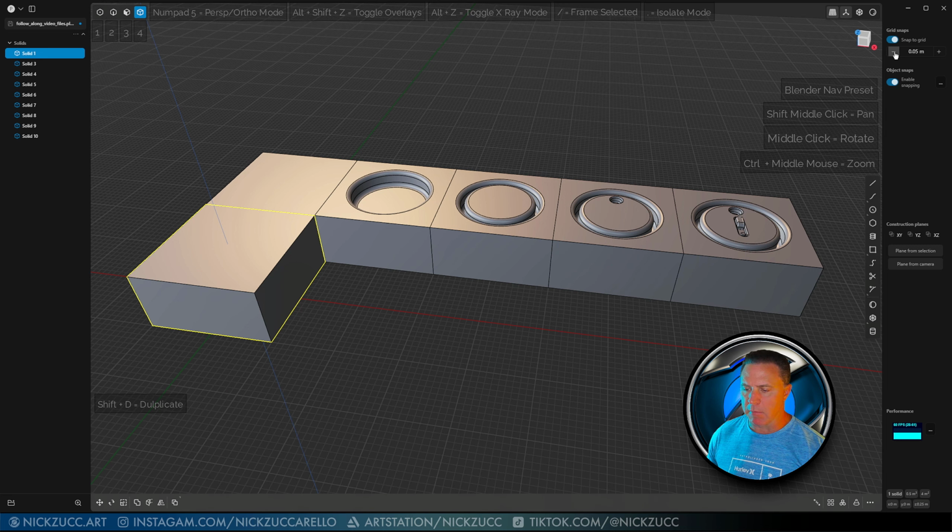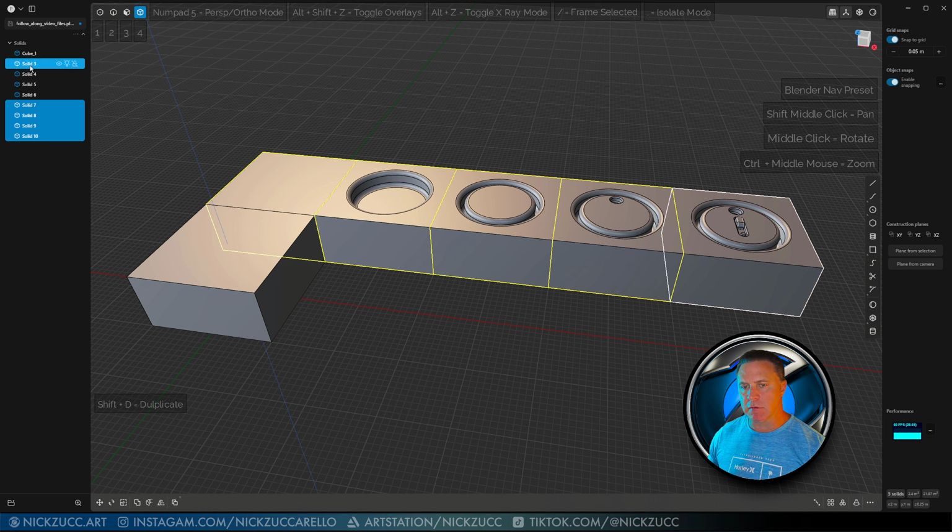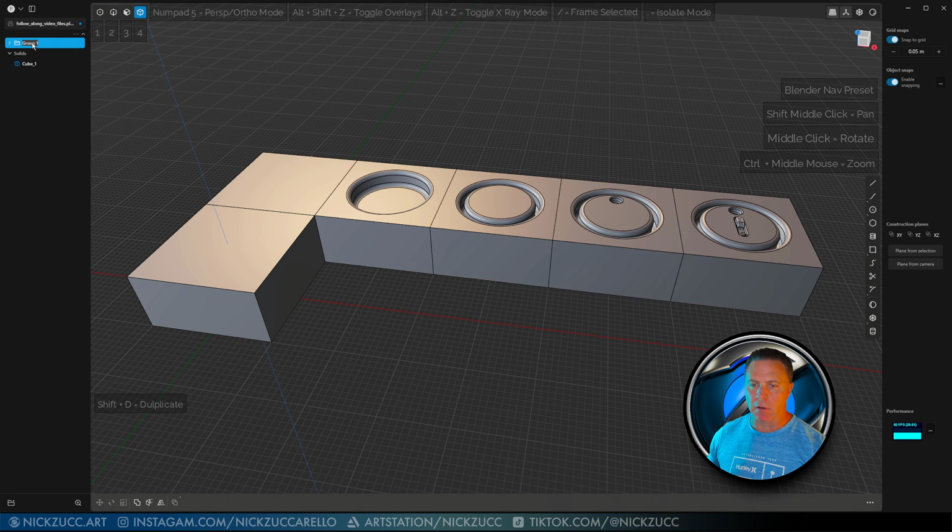And then if I want to put all of these in a group, just to have as reference, let's grab all these parts and pieces that you see here. I can hit Control G, and that will add a new group, and I can call this ref shape. Okay, and now I can turn on and off the visibility of this. I can lock it so that I can't select it. You could do it that way to have different drawing modes within there.